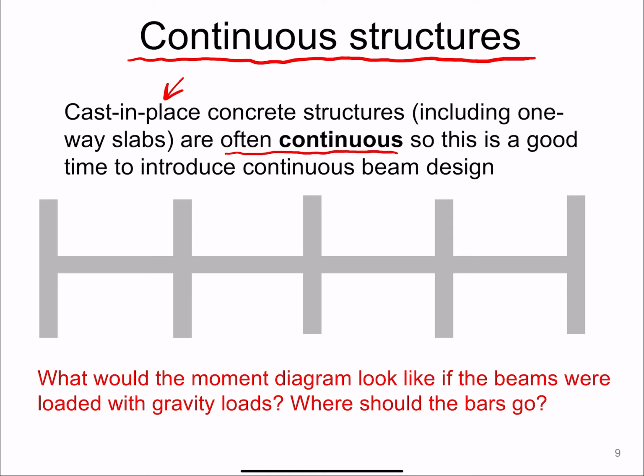You can have this sort of system, as opposed to some precast systems, which I think we were talking about earlier, in which you leave this sort of element called corbels. This is precast construction. This is just a cut. Your columns are prepared with these so-called corbels, which seem like a support. Then all you have to do is go to the precaster and order a precast beam, and you just sit it like this.